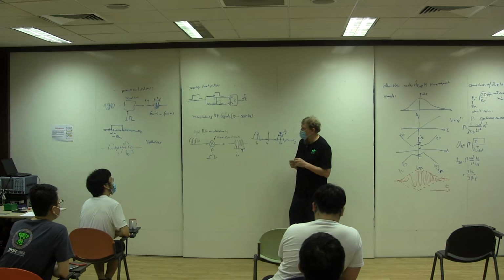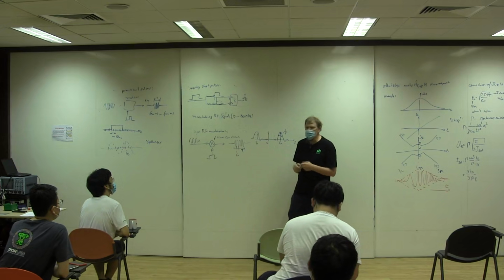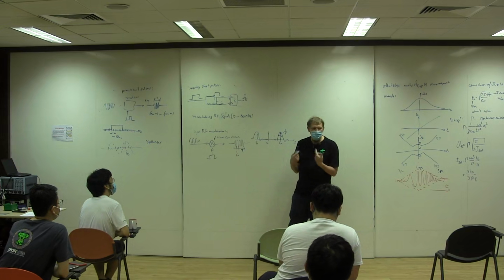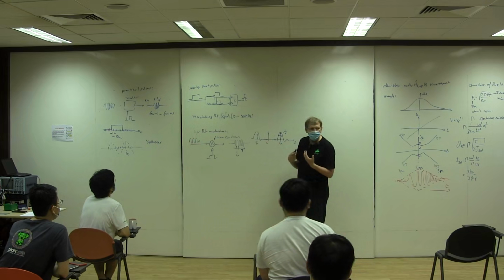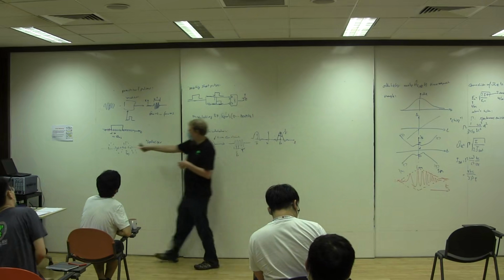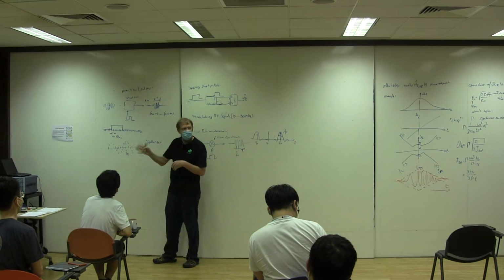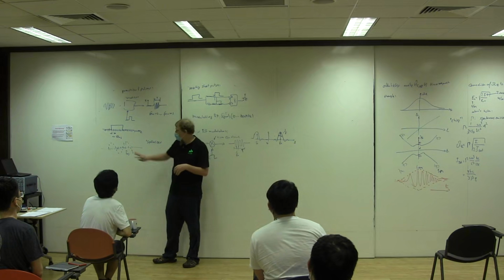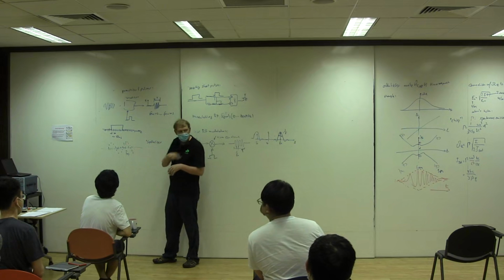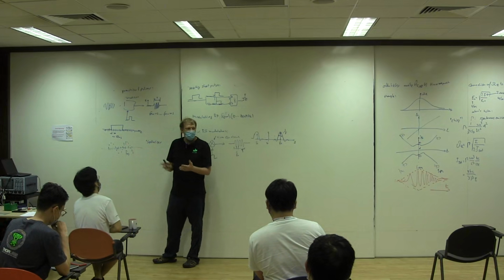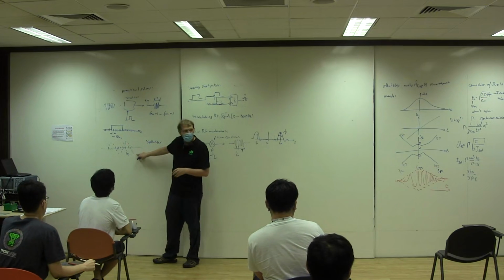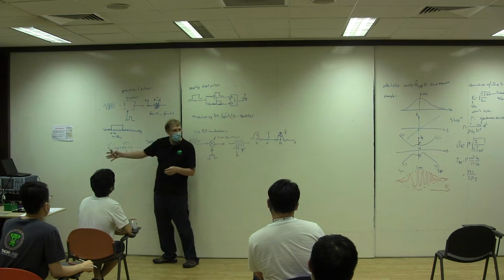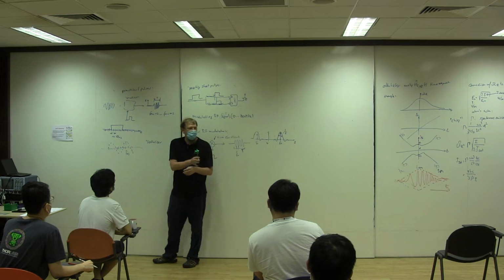Sometimes you find this also for some of these synthesizers. They sample the wavefront they want to generate with a particular rate, and in order to make a really nice sine wave out of the sampled version, there's a filter that removes high frequency parts. That filter lets all the low frequencies pass through, and the high frequencies get suppressed.